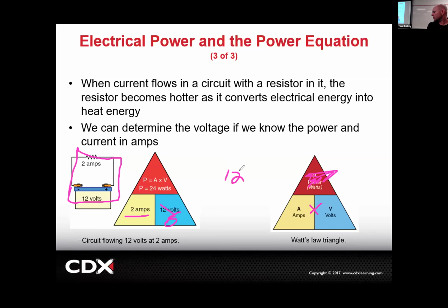What do you think that motor is going to sound like, and what are you going to see? How are you going to know there's something wrong there? Slow and weak, exactly. So when the motor's slow and weak, you're kind of like, I wonder if it's not getting full voltage. It's probably not getting full voltage due to unwanted resistance, right? Unwanted resistance is the number one thing we see. But now you can physically see why it would cause that motor to be weak. It's not getting the correct volts. Technically, it's not going to get the correct amps either. Volts and amps go together, right?